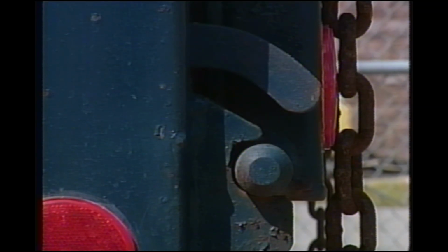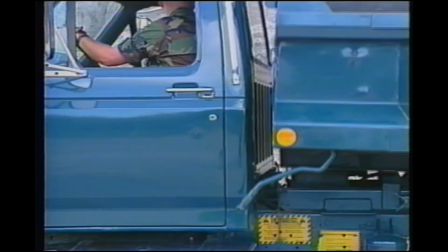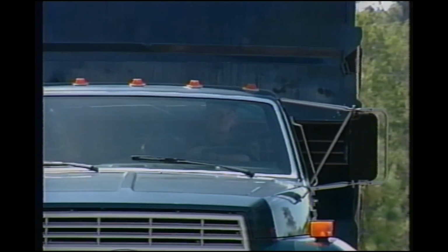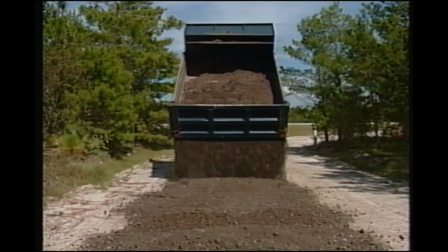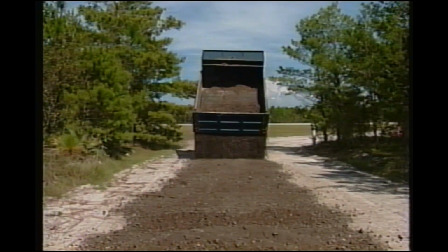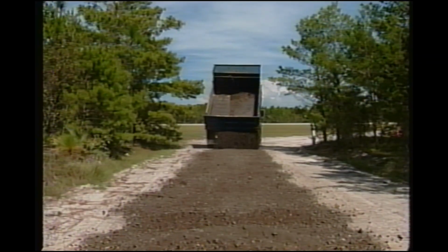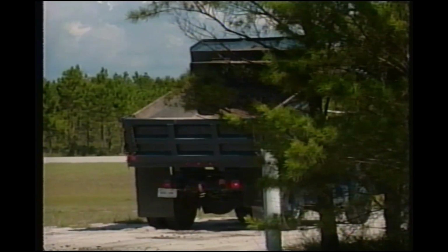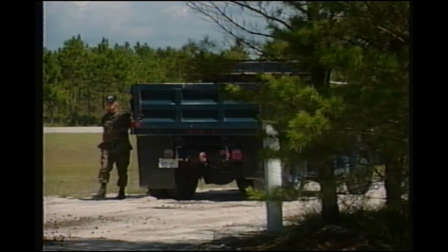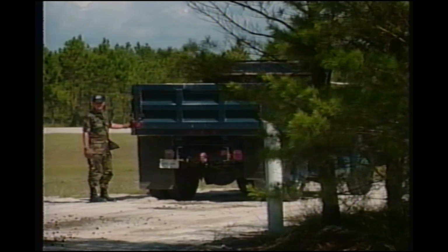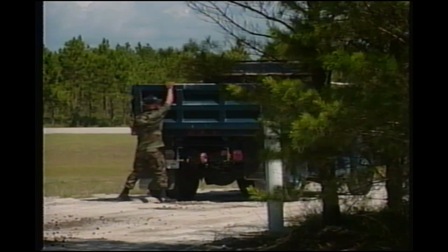Unlock the tailgate. Engage the PTO and pump control to raise the bed. Check in front of the truck and pull forward when the material starts to flow onto the ground. Maintain a constant speed for a more even distribution. At the end of the pass, lower the bed, disengage the PTO, relatch the tailgate, and check to see if another load is required.